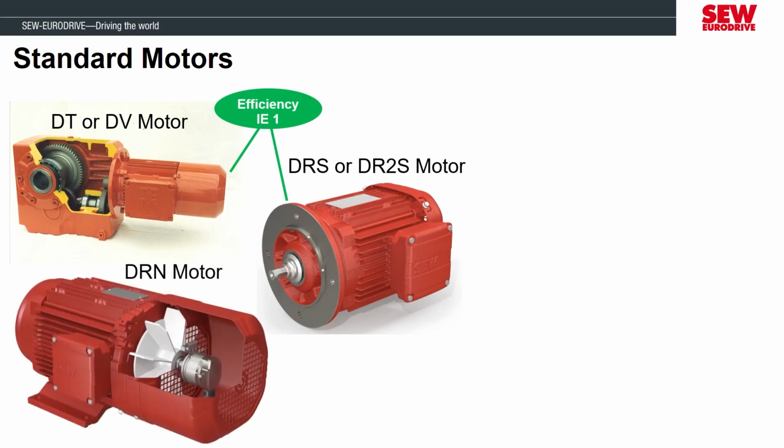The most common standard motor you will see is our DRN motor. This motor meets an IE3 premium efficiency rating. Each country has their own power efficiency regulations, and these are becoming more strict. Starting in 2016, the United States required motors larger than 1 horsepower to be premium efficient. So any new equipment you have that has a motor 1 horsepower or greater is likely a DRN motor.